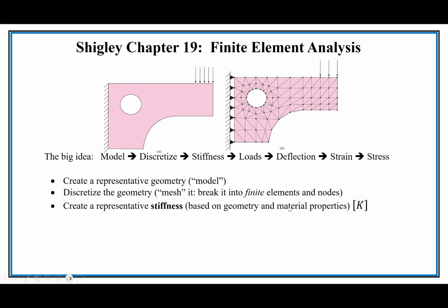And we create this stiffness matrix called K. It's a symmetric matrix, in the simplest case a 2x2 matrix. It could be a larger 3x3 matrix or a 1,000 by 1,000 matrix, but it's a big matrix, this K. And we apply these constraints, which would be loads and boundary conditions, and then solve the equation F equals K times U, where U is the displacement.